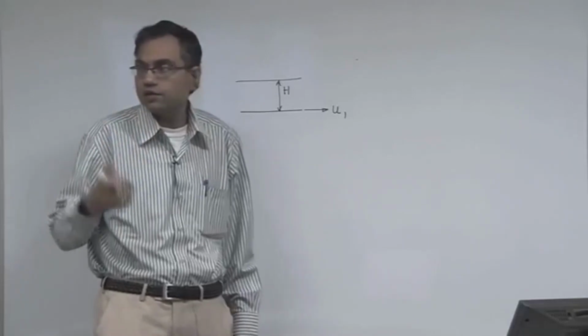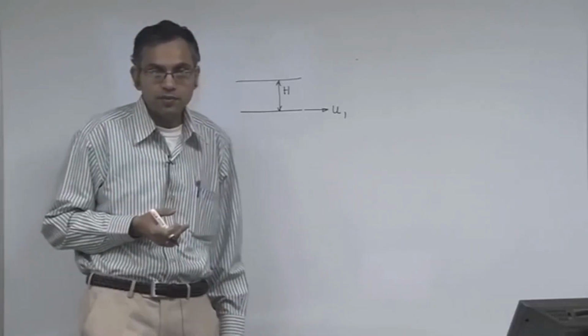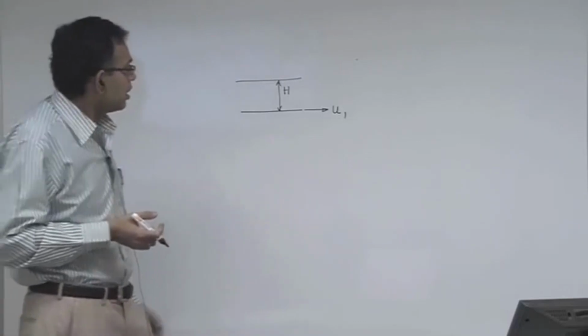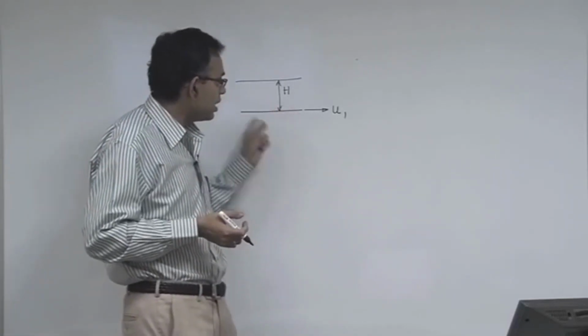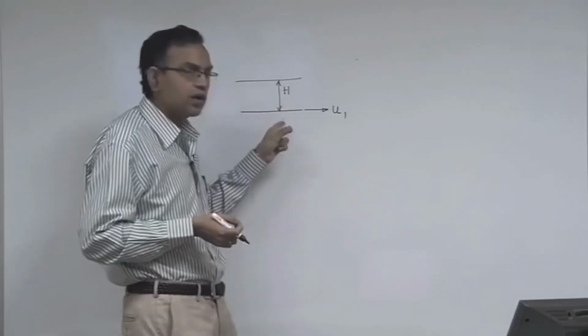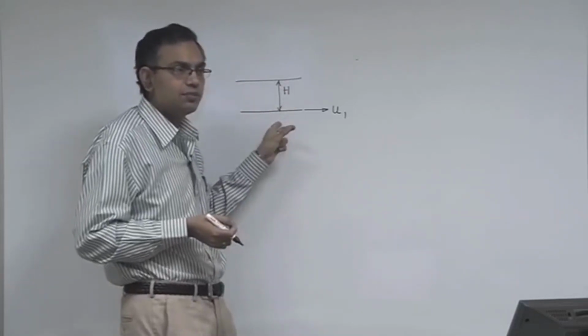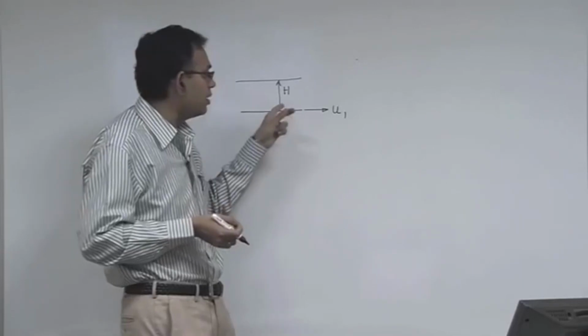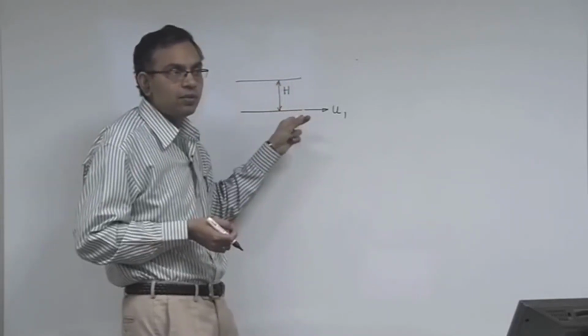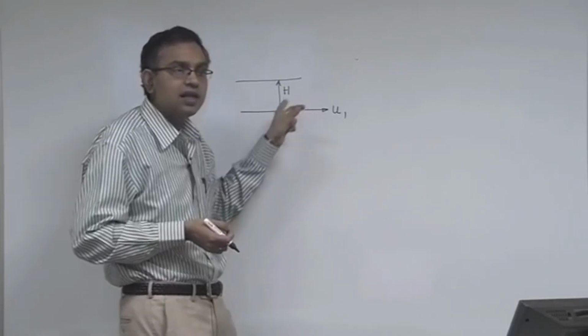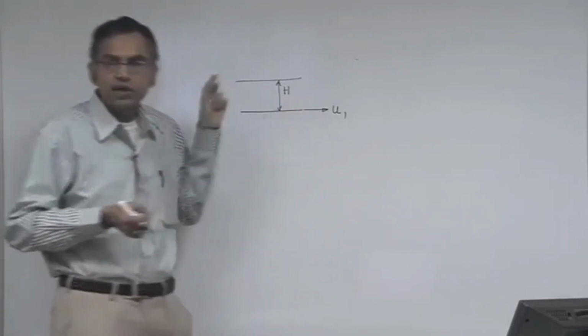It is a modified version of the Stokes first problem, or in terms of the classical Couette flow, it is like a Couette flow. It is basically a Couette flow because you have two parallel plates, one plate moving relative to the other, but we are interested in the unsteady state solution of the Couette flow problem.